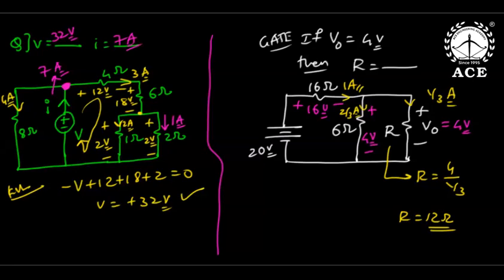In the first question of today, that homework question, sir, why is node V5 not equal to V6? Because of mirror image symmetry? Listen, see, it is on the same axis. Now the left side node is subjected to higher voltage and the right side node to lower potential, if you give voltage between A and C. But the up and down mirror image is equal, because the resistances looking upside and downside are equal.